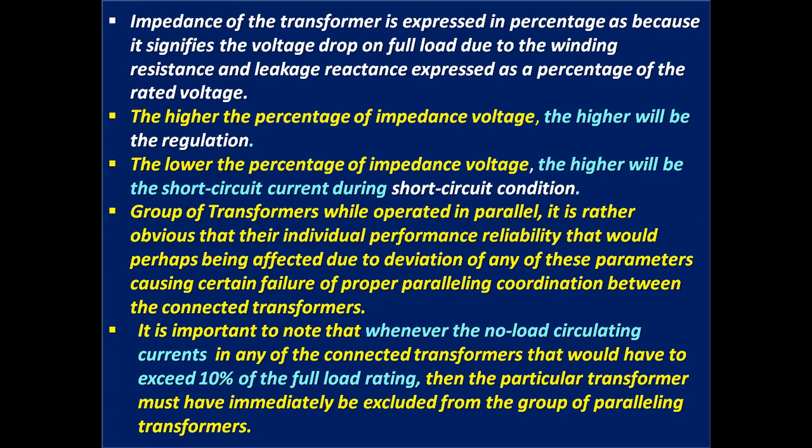The higher the percentage of impedance voltage, the higher will be the regulation. The lower the percentage of impedance voltage, the higher will be the short circuit current during short circuit condition.